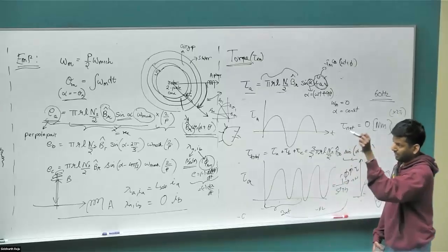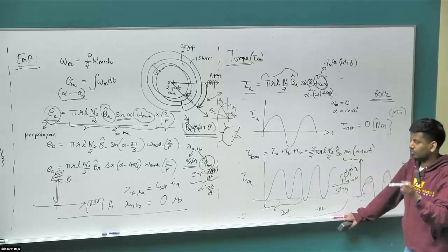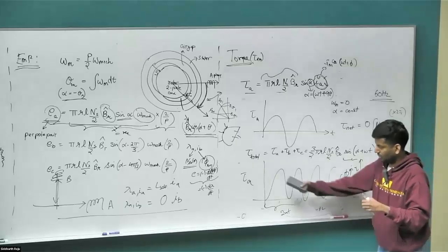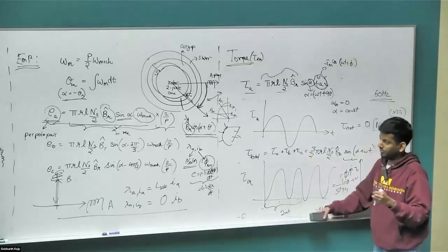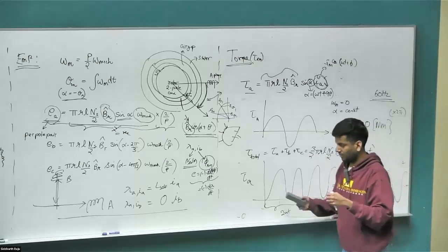When we go to an induction motor, there is a way that we can reduce this oscillation, because the magnetic field rotating in the opposite direction would encounter a lot of impedance compared to the magnetic field rotating in one direction, so it would produce much lower currents and then much lower torque. So in the case of an induction motor, you can reduce the amount of oscillation. That's why you quite often find one-phase induction motors, but never a one-phase permanent magnet synchronous motor.